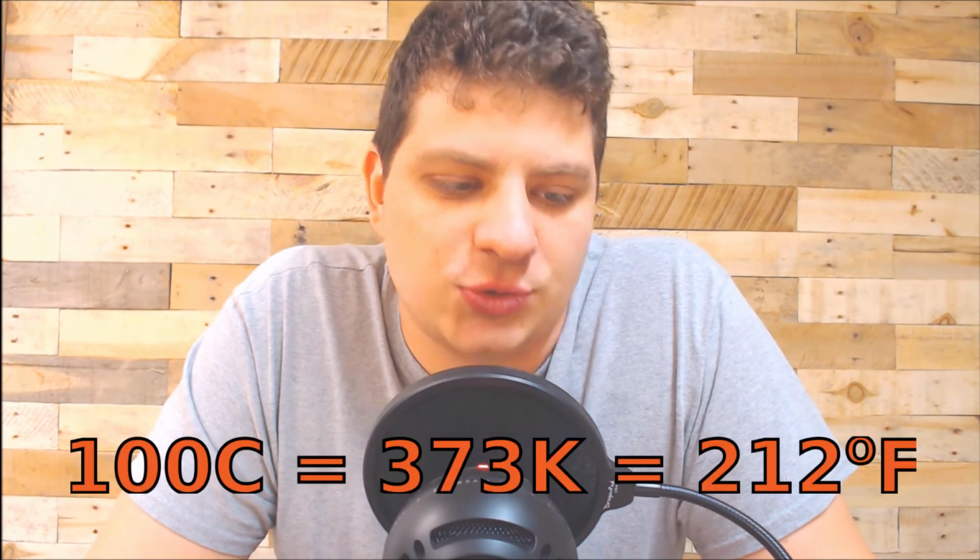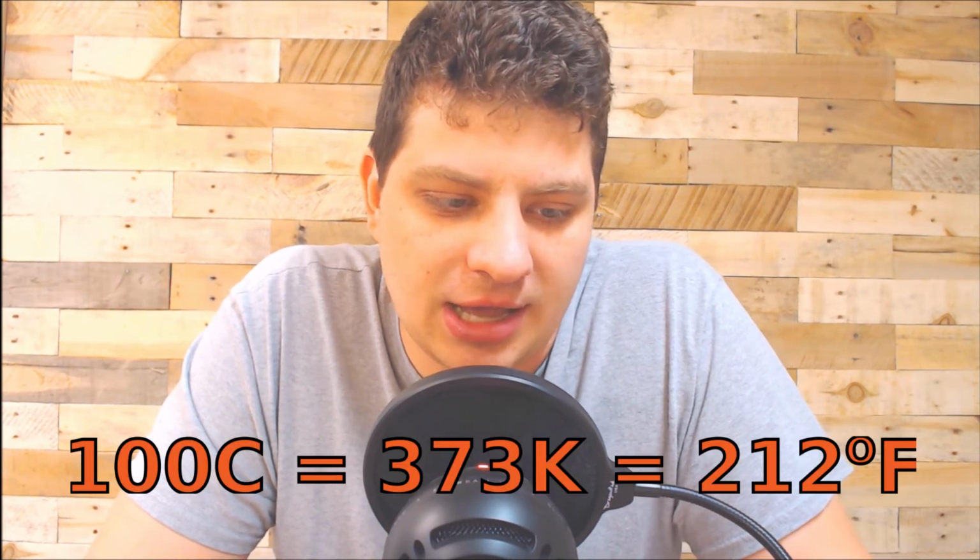Fortunately, we can pulse the fuel as it goes into the engine and pulse combustion. So sometimes it's burning, sometimes it's not. And if we do that right, we can keep an average temperature of combustion lower. We can keep it down at like 100 degrees C, which a 3D printed engine should be able to survive, at least for a little while.